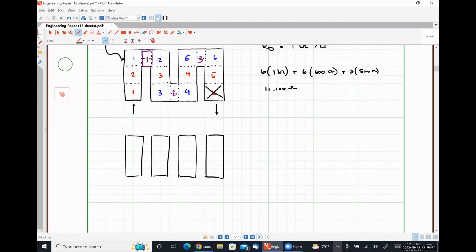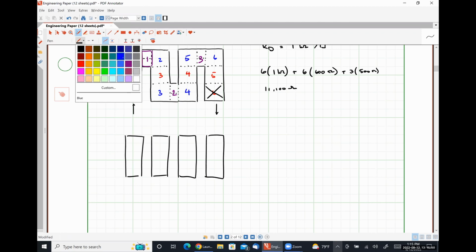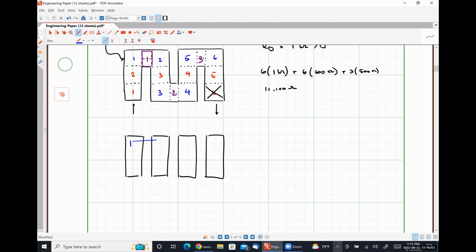So let's say that these are all N-well resistors, and then you connected them to each other using the metal layers, where we haven't really discussed this yet, but as you can probably imagine, the resistance of the metal layer is significantly smaller than the resistance of the N-well layer because it's metal versus semiconductor material. And these metal runs don't really contribute to the overall resistance of this serpentine structure very much.